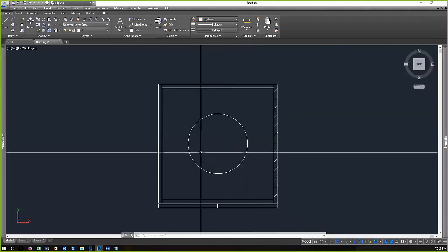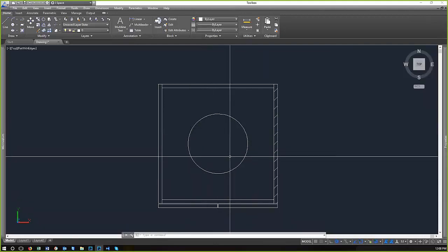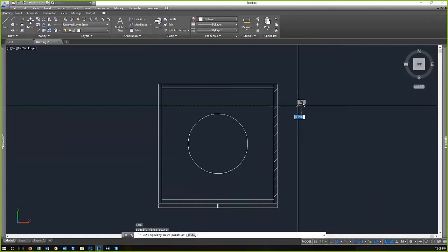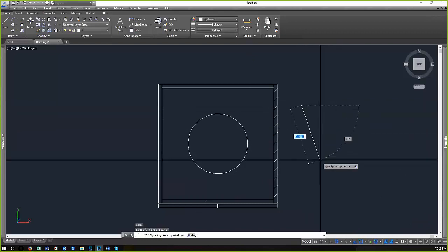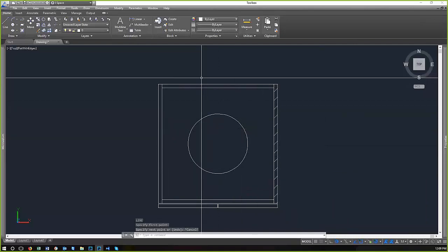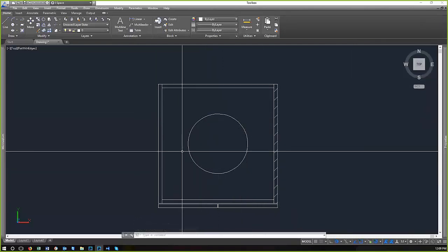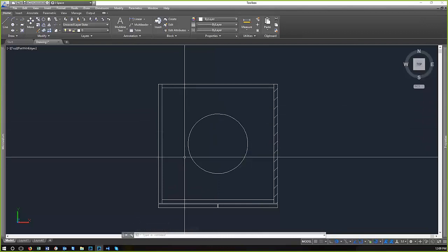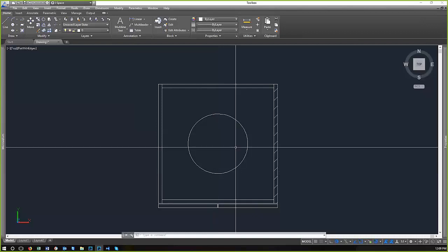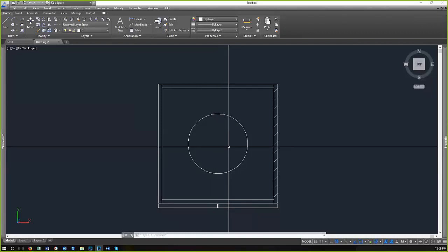But you're going to be using the escape key a lot to cancel out commands. So if you hit a line and you decide that you didn't actually want to use that point, or hit an L, what you do to get out of it is hit escape. And that will always cancel a command and then won't finish it. It'll just get you back to where you were. So I use escape a lot to just get out of commands. But the F1 key is right next to it. So if you end up hitting F1 a lot and you don't really want to, a helpful trick is to just remove the F1 key, and then you stop hitting that.